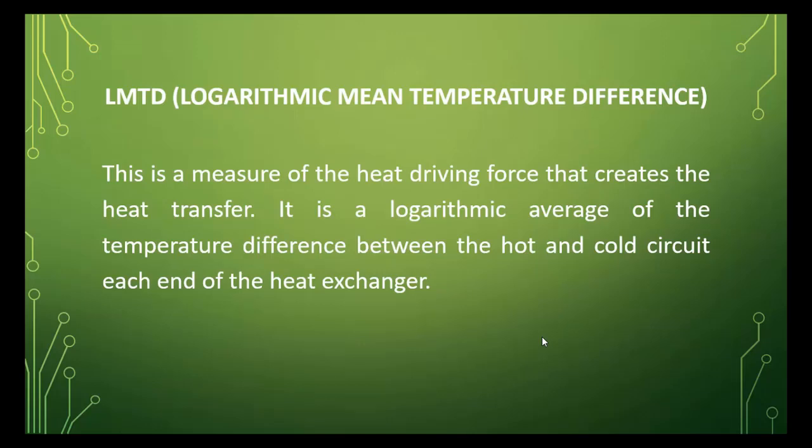LMTD means logarithmic mean temperature difference. This is a measure of heat driving force that creates the heat transfer. It is a logarithmic average of the temperature difference between the hot and cold circuit at each end of the heat exchanger. So again, LMTD means logarithmic mean temperature difference.